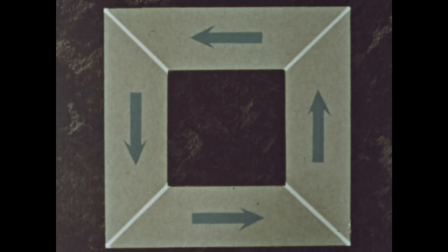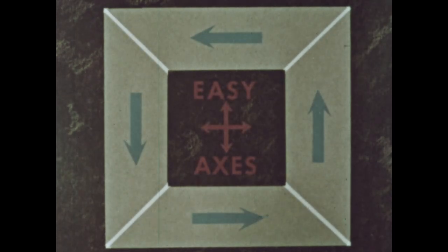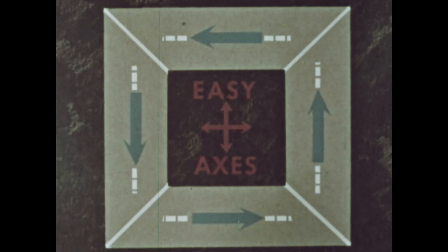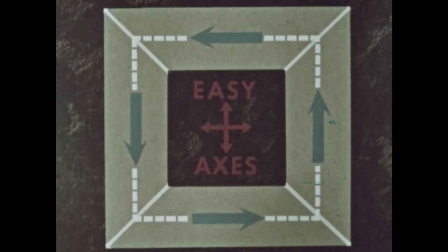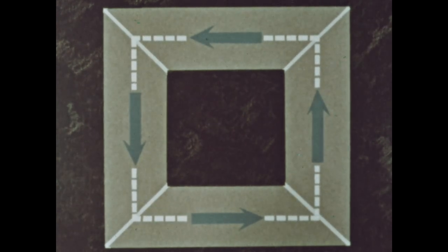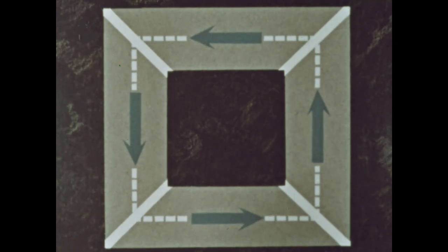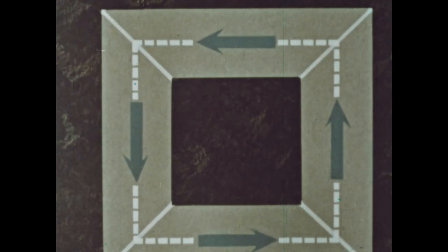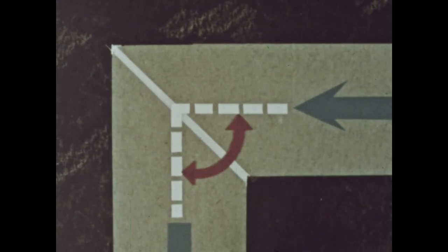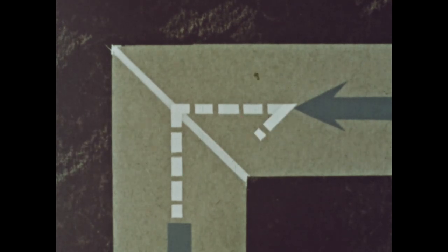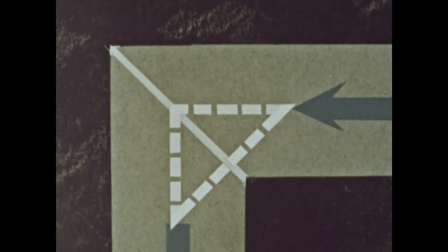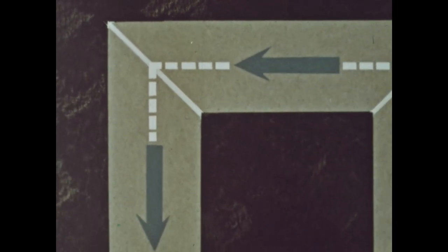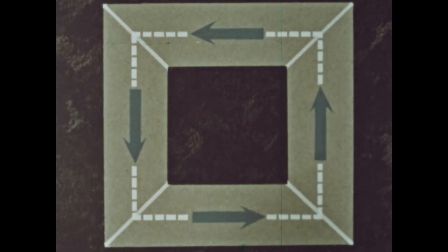Each side may contain a single domain whose magnetization is along an easy axis. The magnetizations are at right angles, and the walls separating domains are called 90-degree walls. Actually, such a wall bisects the angle made by the magnetization vectors so that the components of magnetization normal to the wall are continuous across the wall. Thus, we have a flux loop that does not give rise to H fields.